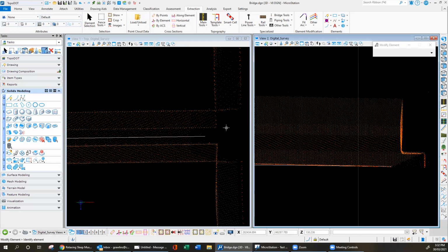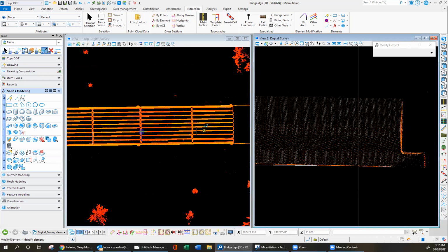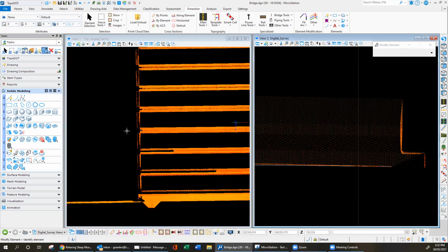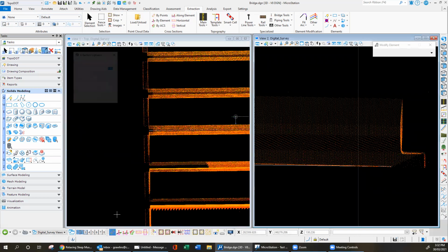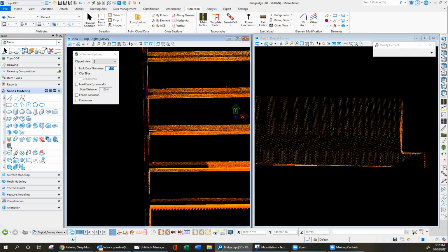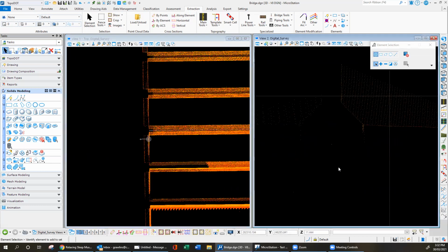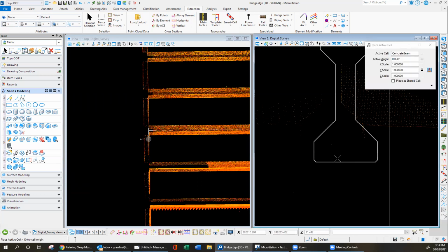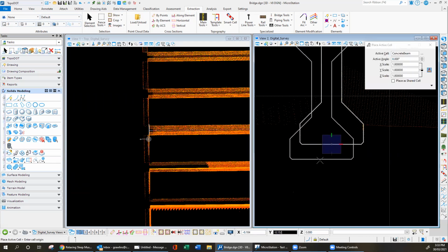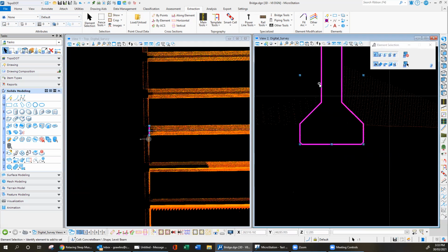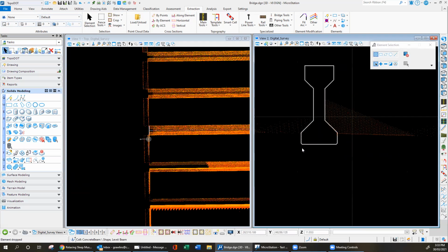The last step in the process again is to extrude the profile along this trace line. So we'll go ahead and cut a cross section through here to make sure that our axis is perpendicular. We should now see our profile line sitting here, and we can pop ourselves a cell, grab our concrete beam, and we'll whack it on there. Go ahead and drop it, so it turns it from a cell to a shape.